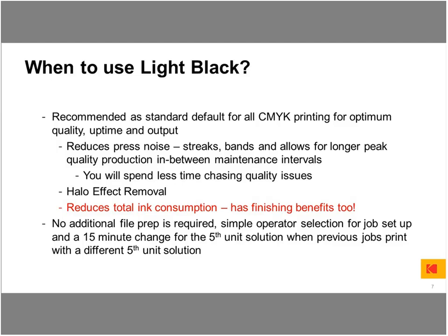And also you want it for the halo effect. The halo effect is what we talked about on the previous slide, that sometimes, if the process adjustment is not 100%, you see a halo artifact around the text border. By using a light black, you will be able to minimize it. Of course, we do have the software fix for the halo effect, but every time there's a toner, a chemical operation is usually more stable.